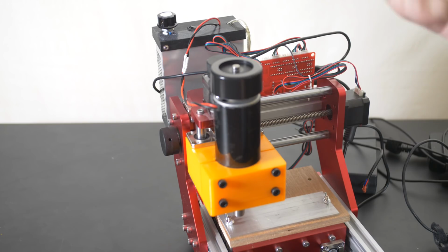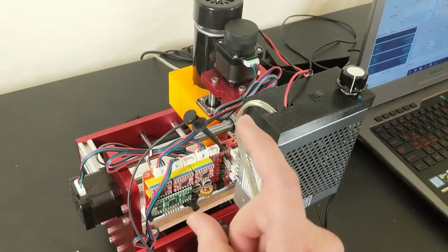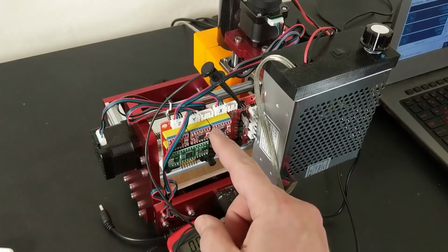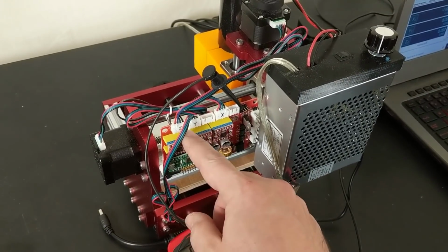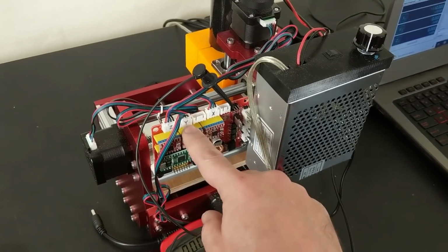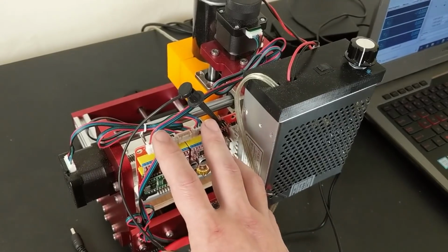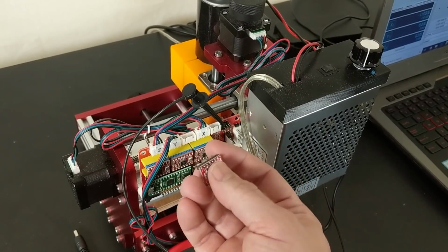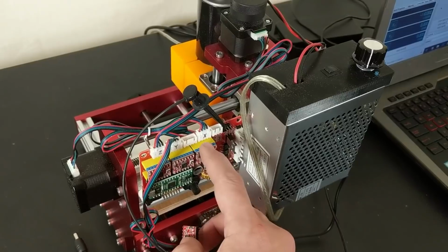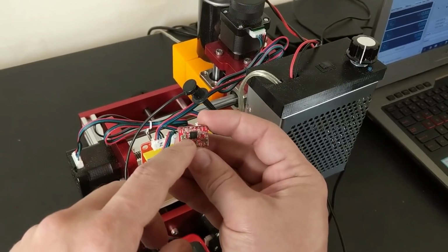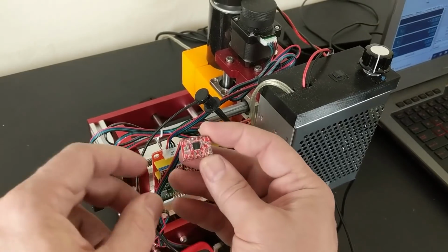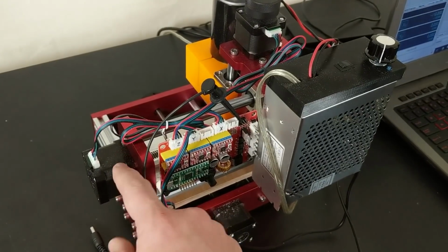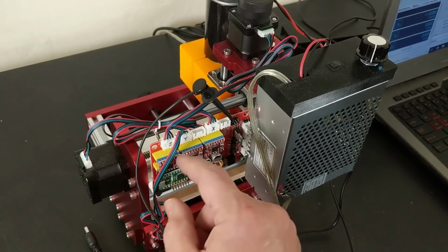So now that the motor's installed, we're ready to cut some metal, but we want to make sure that we're getting the maximum driving force from the stepper motors on this machine. And to do that, we need to turn up the voltage reference, or the VREF, on these A4988 stepper motor drivers. Now this machine that I have here is quite a few months old, so I don't know what you guys are going to get if you order this today, but mine came with these stepper motor drivers, which on the surface are almost indistinguishable from the ones that I've replaced them with. But for some reason, the voltage ref max on this one was 1.1 volts, and these ones get up to 1.8. We don't want to burn up these stepper motors, but we do want to give them as much juice as they can handle. So let me show you how you get VREF.